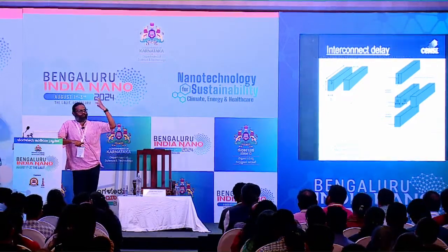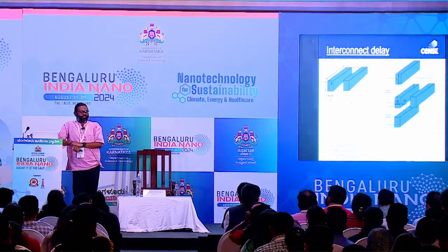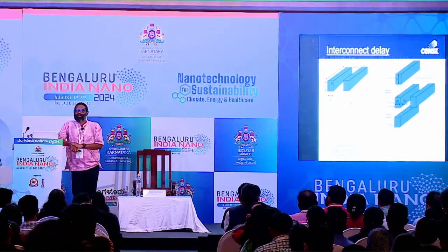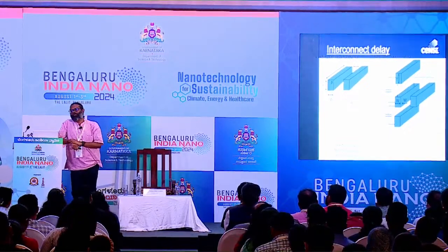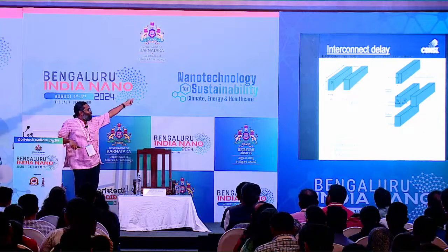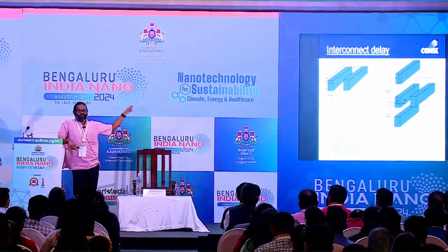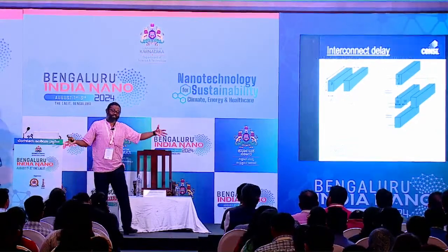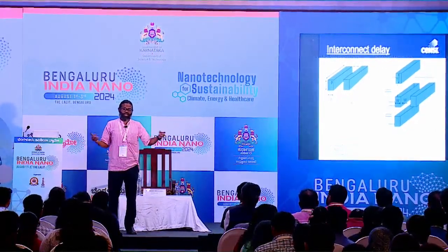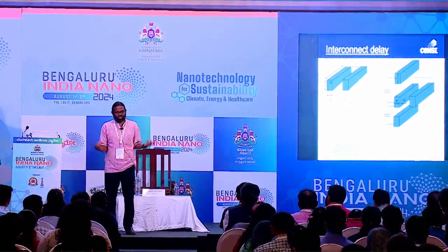You want to operate them with high speed, right? So you look at the clock speed, right? 2 gigahertz, 3 gigahertz. Turbo, I want to push it up to 4 gig, 5 gig, right? That all is limited by this parasitics, okay? The larger number of transistors is great, but then I need to have so many metal lines in order to connect them.